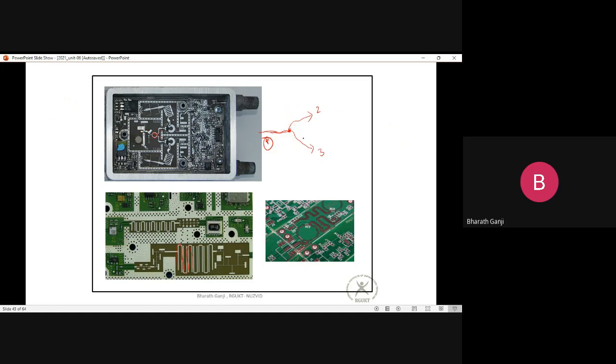But the thing is, the power dividers and all these kind of things are designed in circuits, right? So sometimes you need combining circuits or dividing circuits, and how you design filters at microwave frequencies, this whole thing is done on microstrip lines. On the PCB you can see these wiggly line structures. These are all filter designs, right? So basically these are filters.